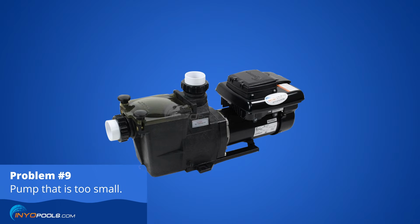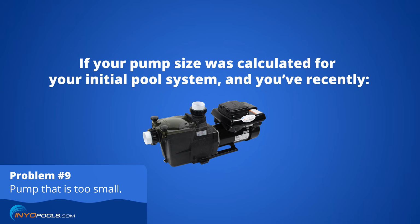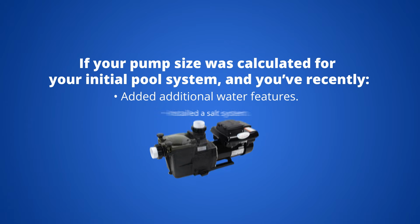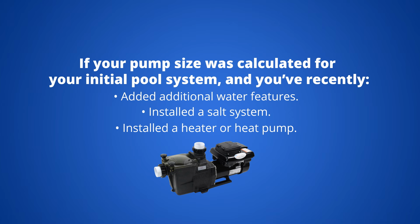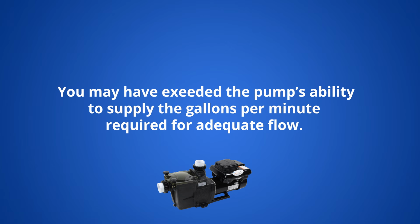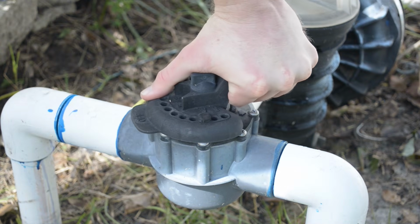Another problem that could cause low water pressure in your pool is a pump that's too small. If your pump size was calculated for your initial pool system and you've recently added additional water features, installed a salt system, installed a heater or heat pump, or moved your pump further away from the pool, you may have exceeded the pump's ability to supply the gallons per minute required for adequate flow. In order to fix this problem, you may need to shut off some of your water features or upgrade your pump's motor or impeller.